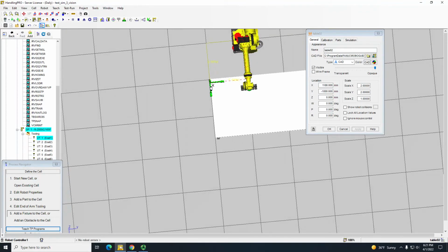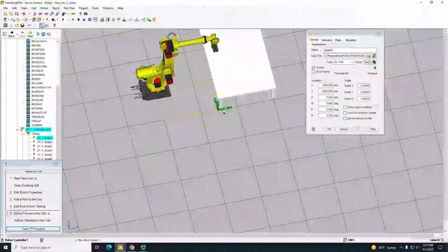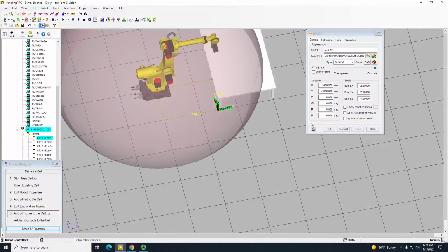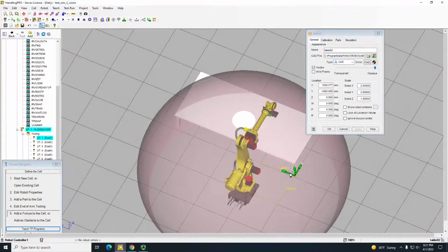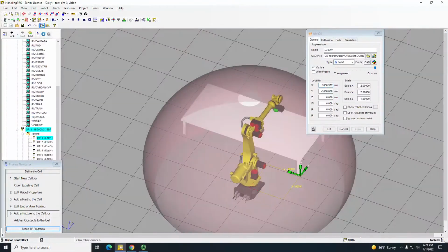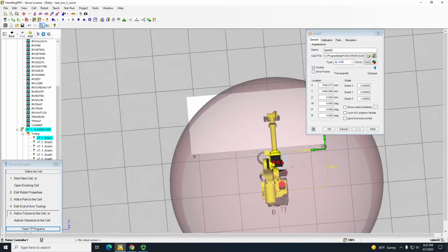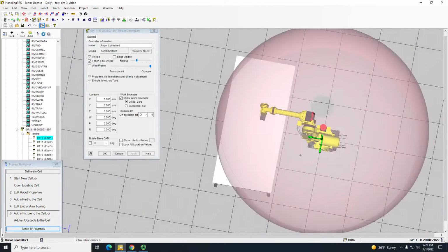So just to make sure my robot has enough reach, make sure the table is in the robot envelope, so we don't have issues teaching frames and all. Okay, sorry, so Z is 0. Just adjust everything in terms of X and Y. Don't give rotation. Alright, so we'll have to move the robot a little, table a little back, I guess.